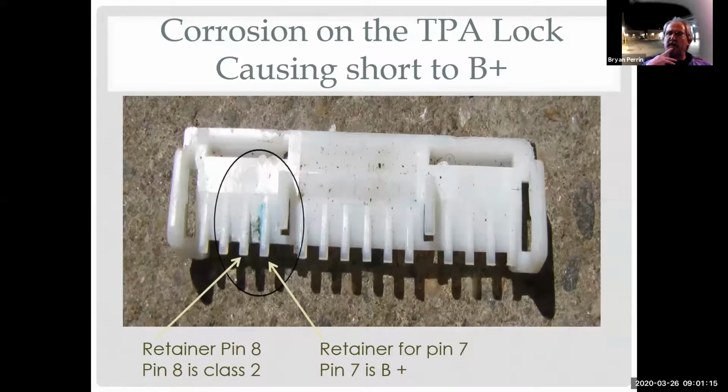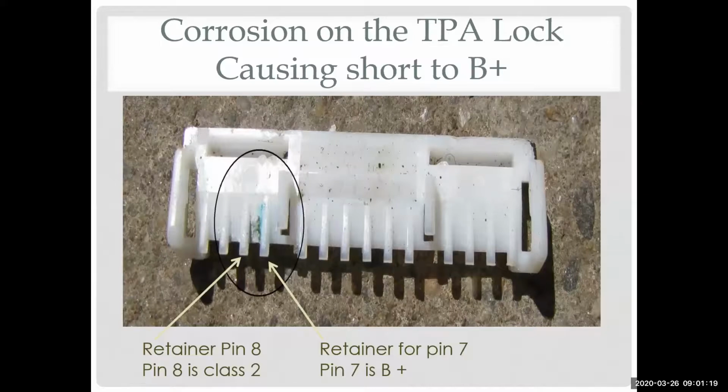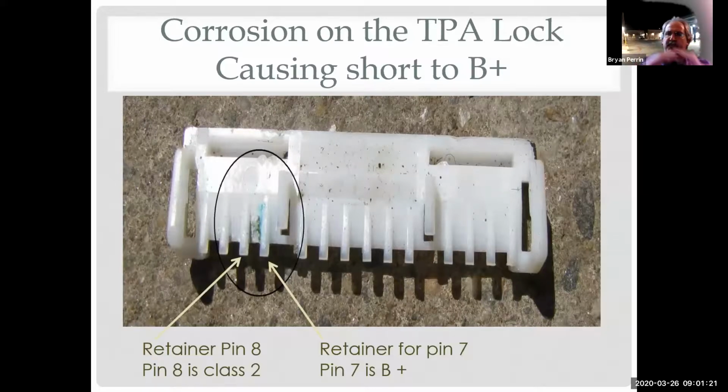I'm not sure what you mean by very close to the connection. The pin needs to fit correctly as far as the male and female parts. If that's loose, you'll get a voltage drop and you'll get heat also because you have resistance there. Is that what we were talking about?